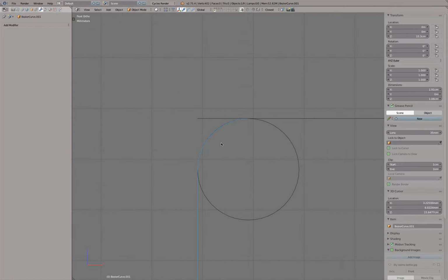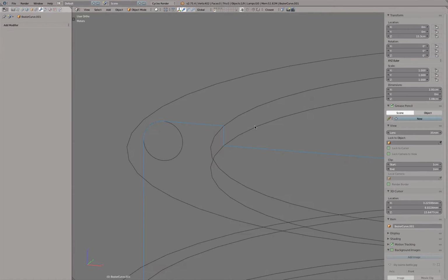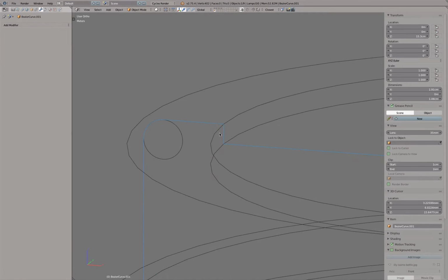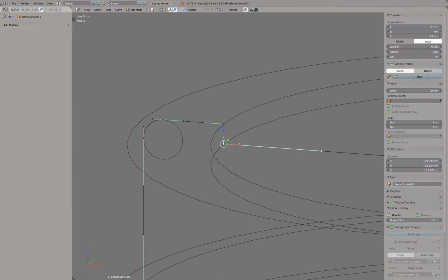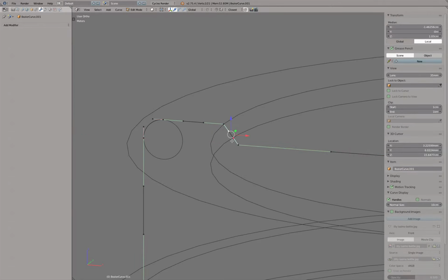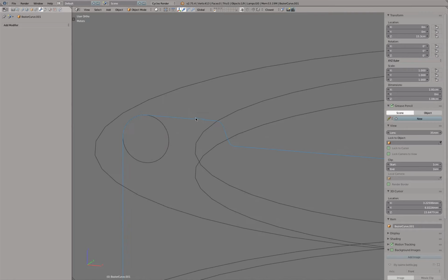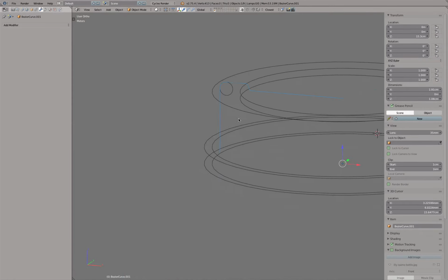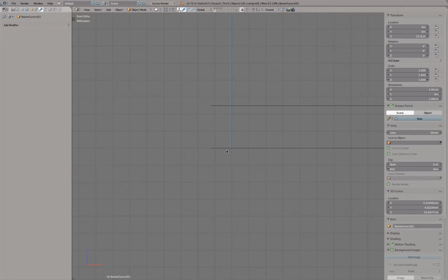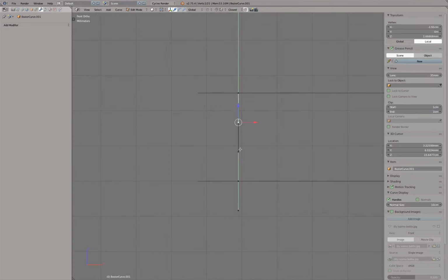There. Now this looks actually a little bit better. For example, down here, this isn't really as stepped, so we could sculpt this a little bit more. These 2 points, for example, we select and say aligned. Oh, look at this. So we have a nice S transition. This looks pretty good. Let's go to here, U2 as well, aligned.